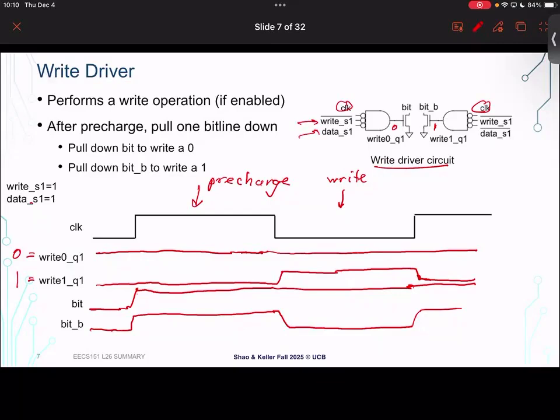We're showing a simpler version of the write driver circuitry here that saves some area, but may impact the writability slightly. In practice, it doesn't matter that much because the side that's 1, as we know, the access transistor really is just not going to do that much, right? So it's contributing so little to the actual writing of the cell that we typically just ignore it in the analysis. But it's a good question.